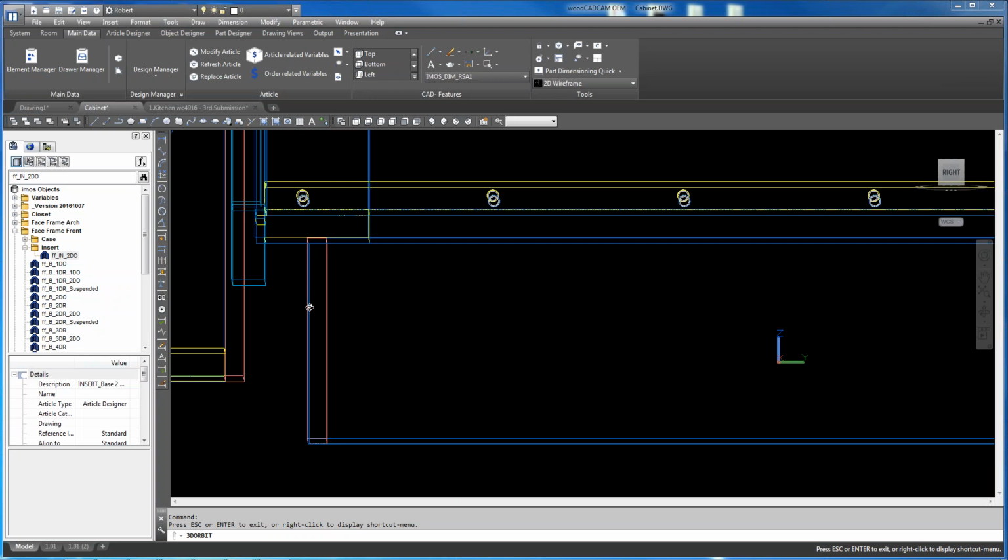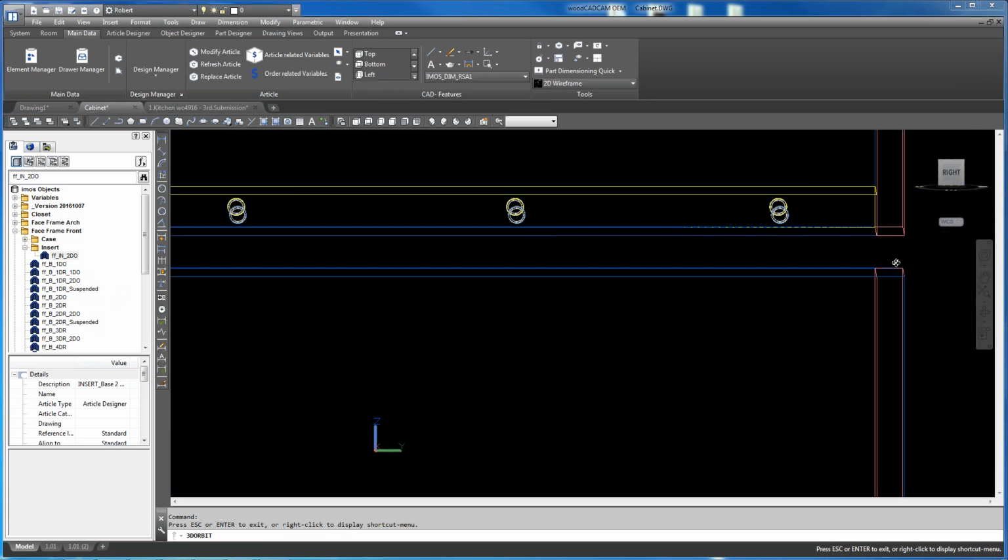So this sub base would be just for my section view, just as a guide. But later on the face of it, we'll apply another piece of wood that I believe I can draw after I have the whole layout of cabinets. So what I would do now is just have this base setback from the face frame by 3 3/4, and be sitting directly on my box.